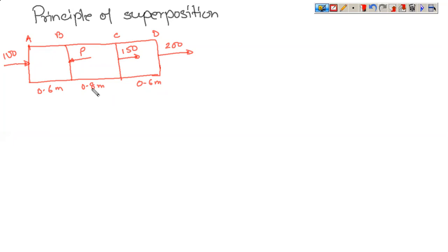You may have the suspension system also resting on it at different locations. So the engine load is exactly at the middle. You have suspension load at the ends. You have radiator load at the other end, and you have foundation bolts, with the help of which you are tightening the chassis to the car frame.